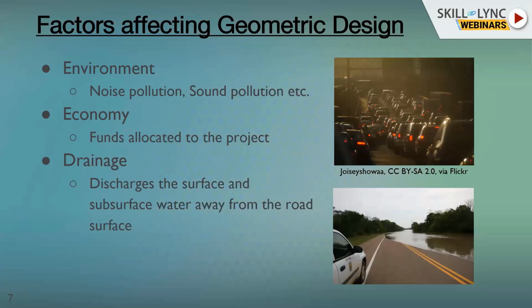And as I told you, economy is a self-explanatory thing. You always have to design your road at the very minimal cost. Economy in terms of geometric design means you have to minimize the earthworks.